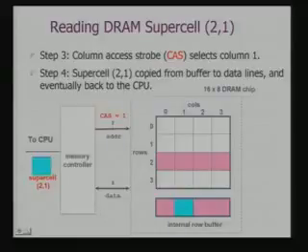Similar is your write operation. In fact, read operation has another interesting feature to note: the refresh operation is normally nothing but a dummy read. If I do a dummy read, I can actually refresh the cells.